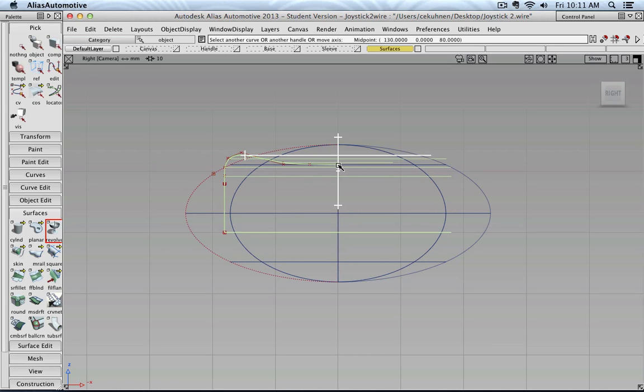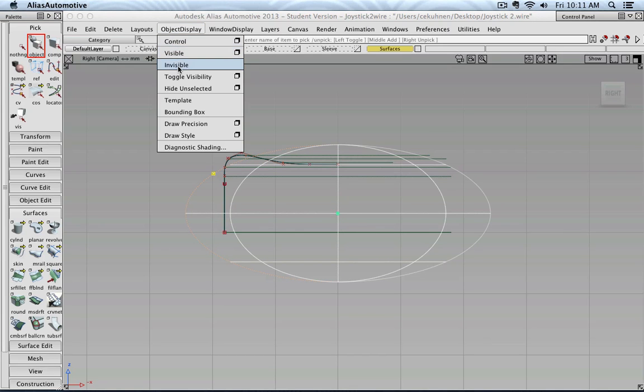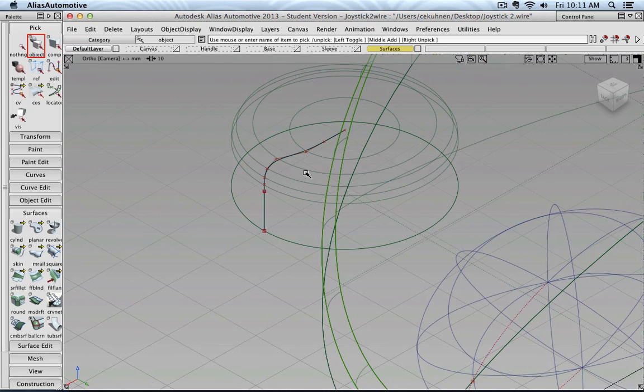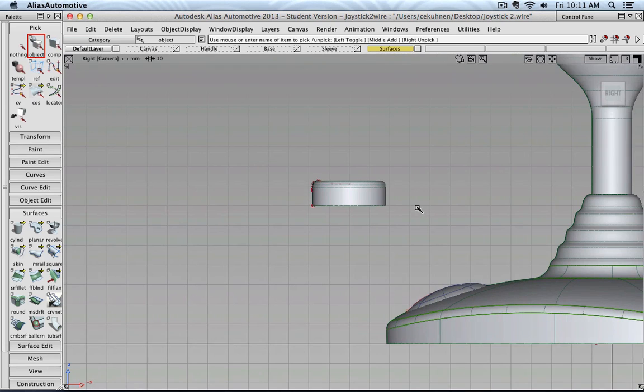And because this point is snapped to this grid and I snap the center axis to the grid, my revolve is complete and I do not have, for example, an opening in the top part. So when I go into perspective view and then turn on hardware shading, you see this is closed. So the button actually doesn't look too bad.